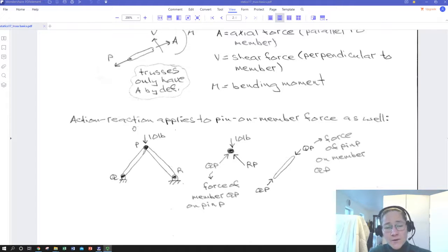So also remember things like distributed loads. If we had water or wind blowing down on this such that we had a distributed load down this member, we also wouldn't have something that we could analyze like a truss. It would still be slender, but we'd have to analyze it with our more general conditions of equilibrium. We couldn't use all our shortcuts that we do for a truss because those only work for two-force members.